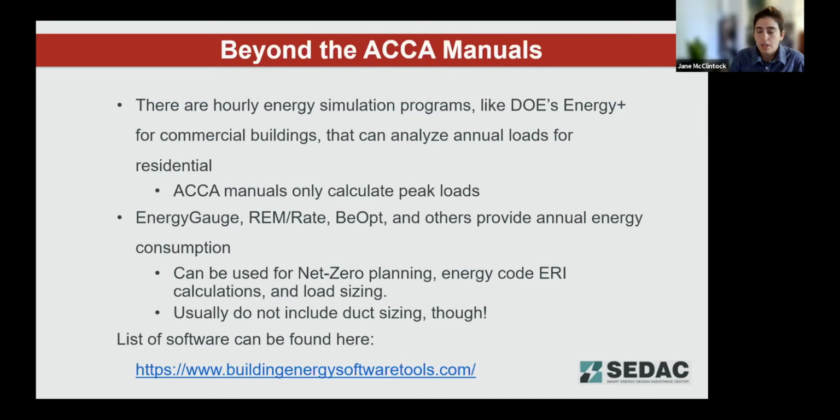But we also want equipment to perform well on an average day. So if we do this kind of analysis, we may be able to better design a system that, for instance, has a high fire and a low fire to ensure that it's able to perform efficiently on the most common design condition, not just those extreme days.